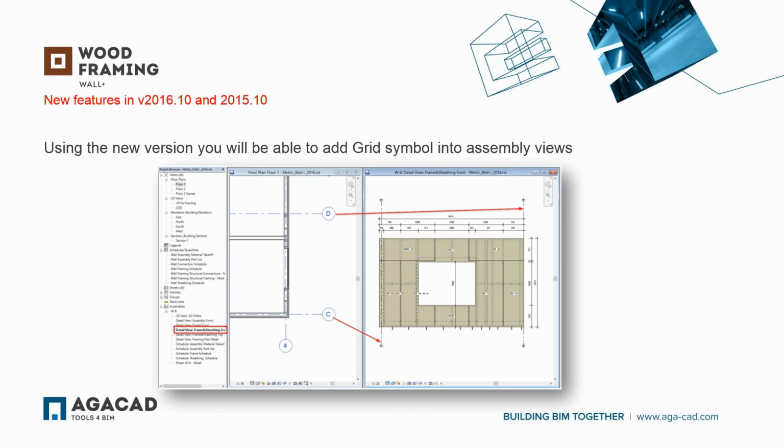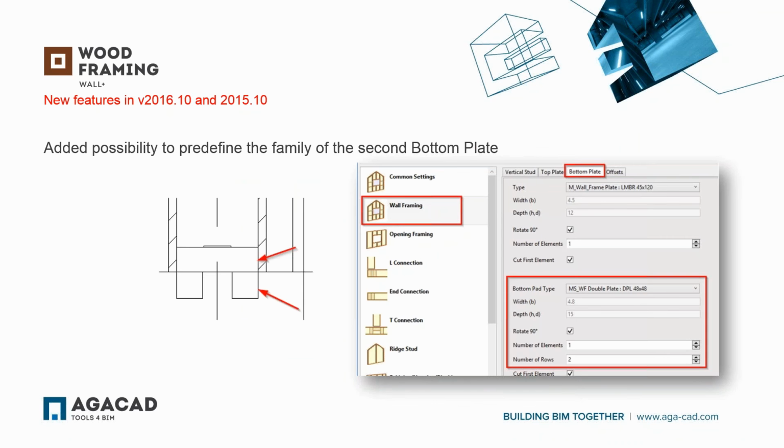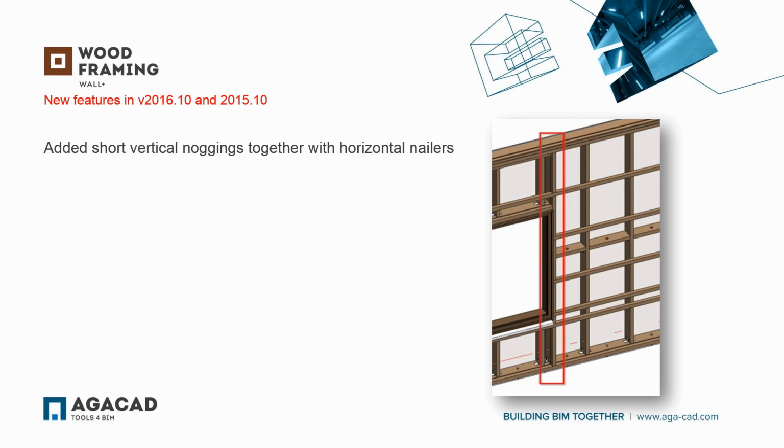Actually, this is not a regular grid, because you know that into the assembly you can't add a regular grid, as it is not allowed by Revit. But here we added the possibility. We have created a special grid symbol and we're adding it automatically into the assembly views. Then, as we talked today, we added the possibility to control the bottom plates, and you can predefine a totally different family for the bottom plates, and you can even have such a bottom frame. Then we added the possibility to control noggings together with the horizontal nailers,